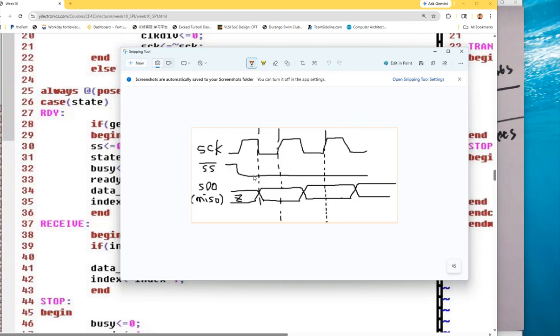And the SPI follower transmitter module inside is detecting that falling edge. Always at the negative edge of the SCK, right? Then it goes to its state machine and checks: a falling edge came, but I still want to see if the chip select is low. Is the chip select low? Yes, because it's already enabled, it's low. So the follower transmitter sees this condition satisfied. Falling edge, and also the chip select is low. What is the follower transmitter in the ADC going to do? It's going to place the data on the data line, and it does it.